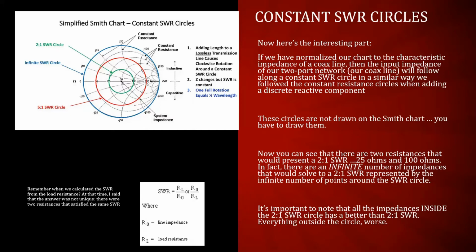And likewise, if you continue going on, you will get back at a half wavelength. You'll return back to the point where you started. Every half wavelength that repeats, every quarter wavelength, it sort of inverts. So again, when we looked at this formula before, there were 2 points with that intersection, but it actually is an infinite number of points on the SWR circle.